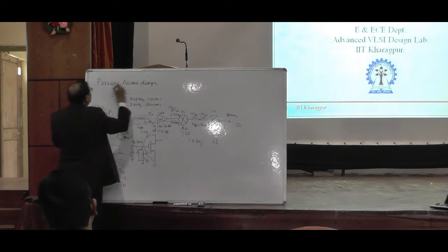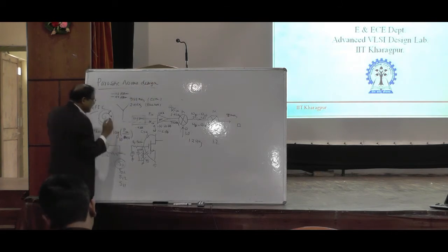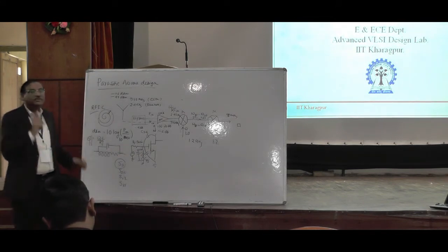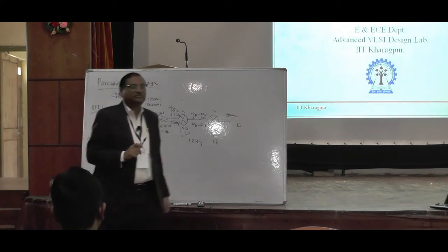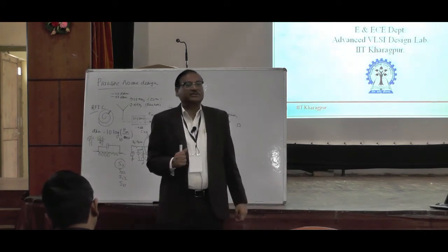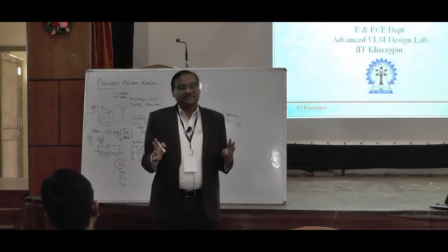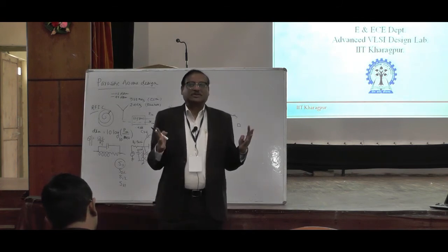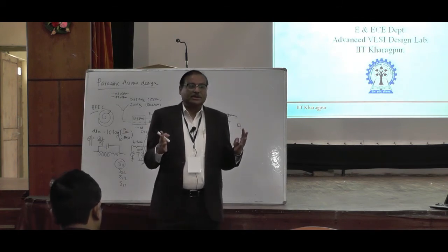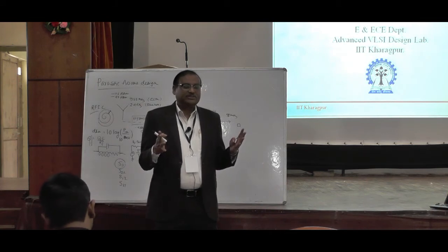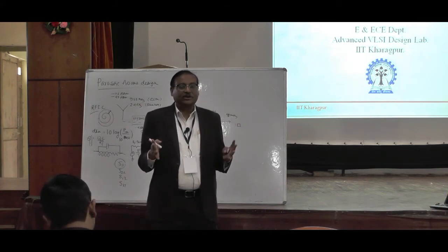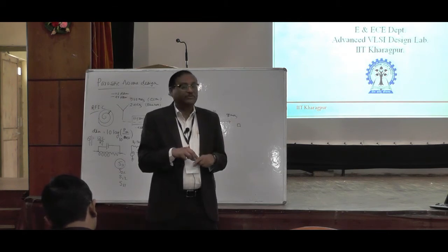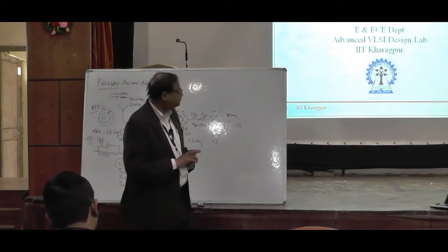If you are not aware of the parasitic effects within the passive components or within the device, your design would not be complete. You might get very exotic results in the ideal case, but that is always frustrating, because if you look at these parasitic effects, your gain, your noise figure, your actual results will suffer from the simulation data.